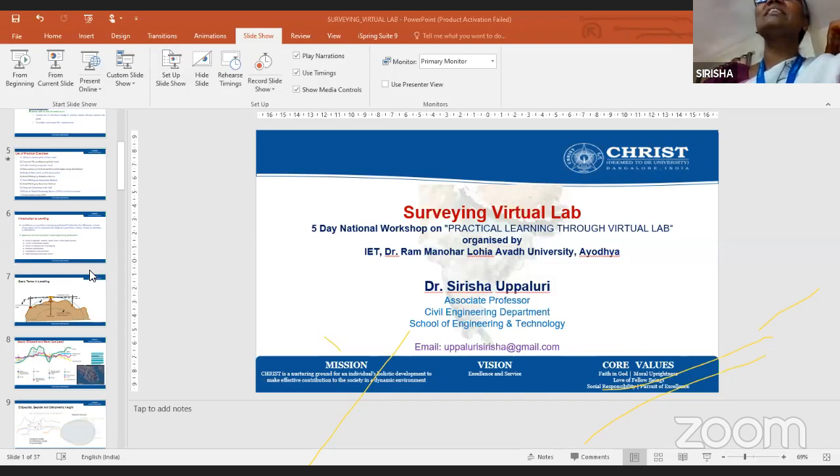You take the approximately 6370 km radius of the earth. The arc length is 250 kilometers. Then you calculate how much difference is coming. D square upon R, we do the curvature calculations. L equal to R theta. If you consider a chord length as an arc length, you can calculate easily how much difference is coming.